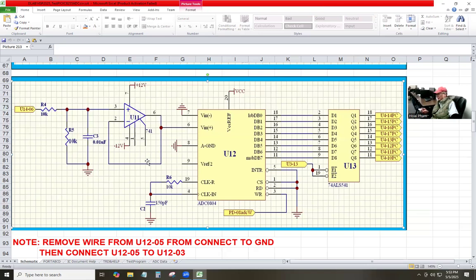Whatever they show here: pin 2 is 5 volts, pin 7 ground, pin 8 ground, pin 9 not connected. And make sure ADC U12 pin 10 must be ground. Just as a DC, just a digital part, they get power, they must get ground.